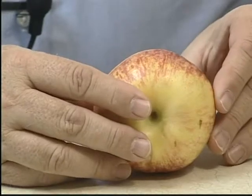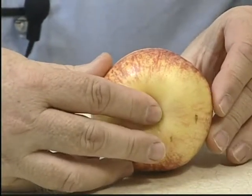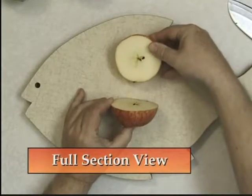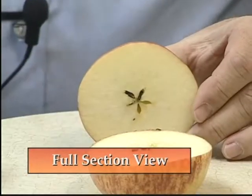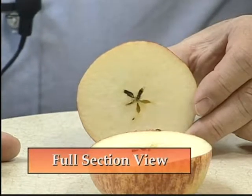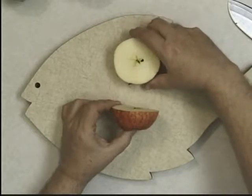Now imagine here that I have this apple in front view and I want to make the top view as a full section view. Top view, I'll just open this up and you see that it's sliced all the way across. Full section view. Not to be confused with a half section view. Let me do another one to show you the half section view.